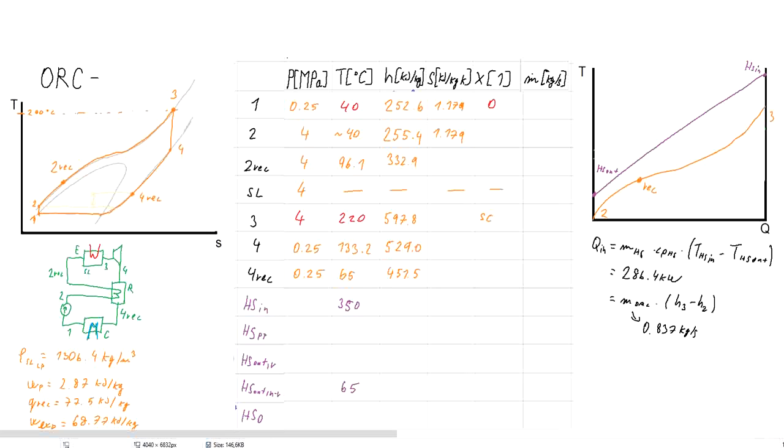So for this case, again probably we could transfer, not in absolute value, but for the part between 2 and 3 we could get perhaps a little bit more heat out of the heat source, because the minimum temperature difference would be most likely at this point. So here the recuperator could bring us some additional power output.